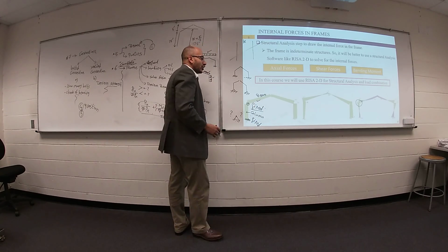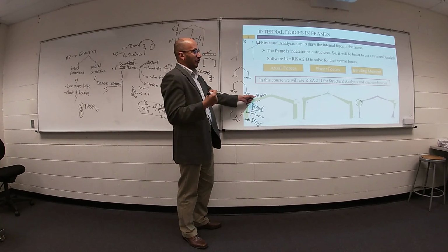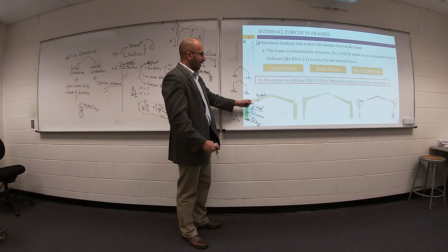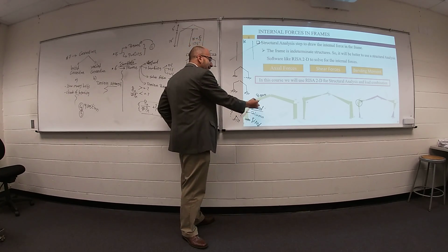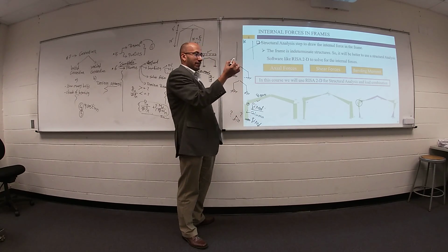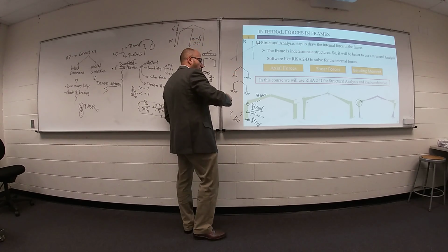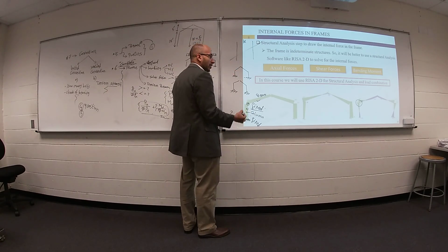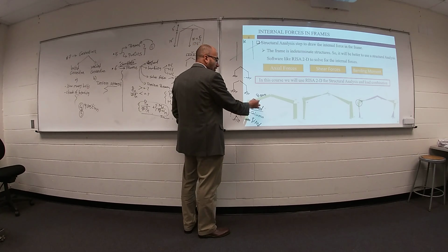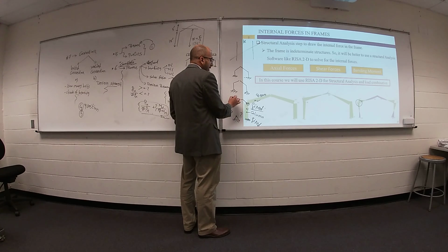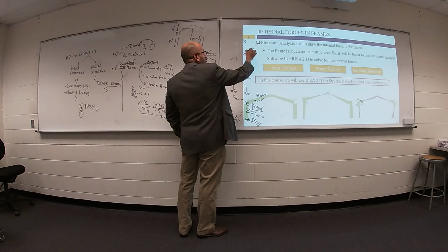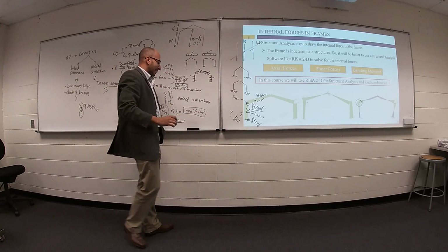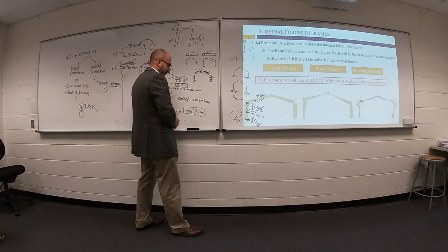If your beam is very stiff compared to your column, that means your beam makes the column fixed. On the opposite side, if your column is much stronger than your beam, that means your beam just supports your column, so it can be thin. Based on the stiffness, I can figure out the value in between. Anyway, it's fixed, okay?